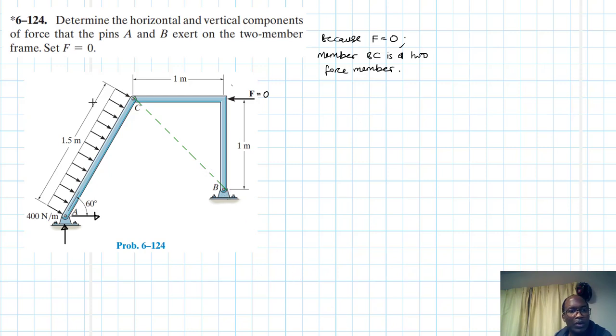A two-force member only has two forces that are collinear and opposite in direction, connecting the two points. So let's assume the reaction is in compression. Here I only expect one reaction force like so. I'll call this B.